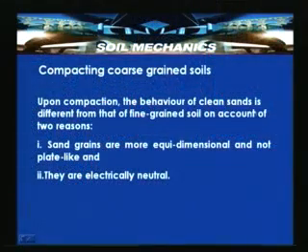So, let us look into this. Upon compaction, the behavior of clean sands, or clean coarse grained soils having fines less than 10%, that is silts and clays less than 10%, differs from fine grained soil for two reasons. The sand grains are more or less equidimensional and not plate like particles, and they are electrically neutral.